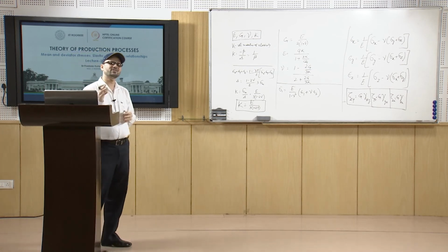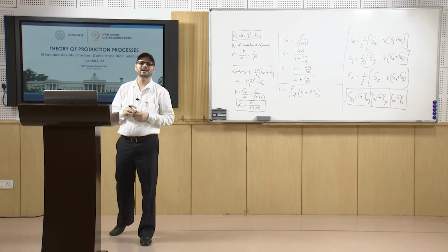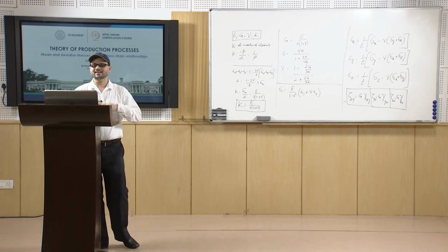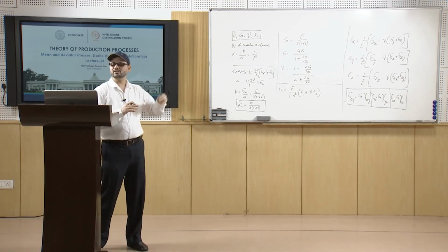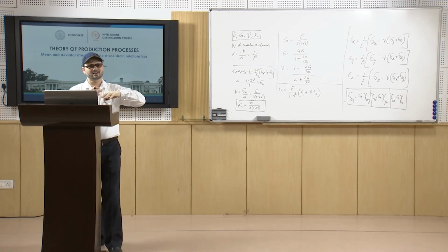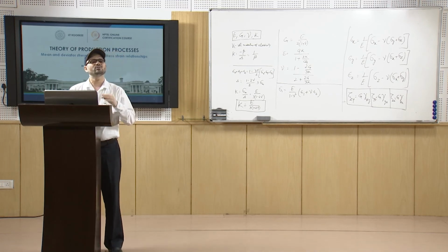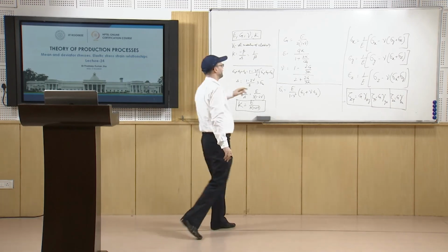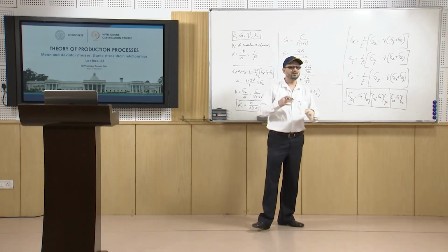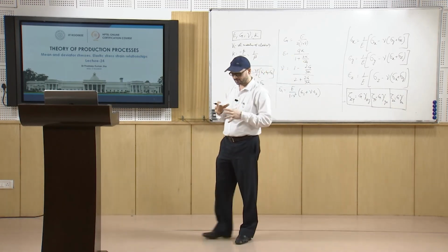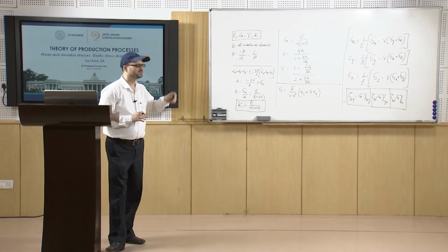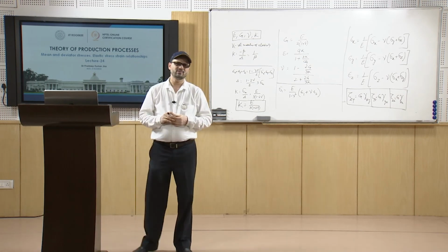In case of plane strain condition, you will have strain in one of the directions as 0, because one of the dimensions may be quite large. In that case, the epsilon 3 expression which we have got earlier can be equated to 0, and you can get the values. So you can get these situations where you have to find the value of stresses from the elastic strain values, and you can use these relationships for finding that.